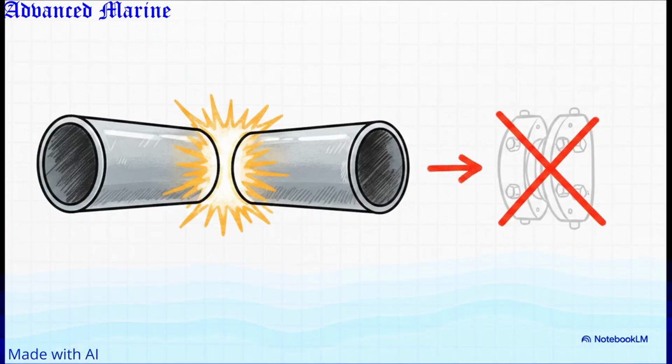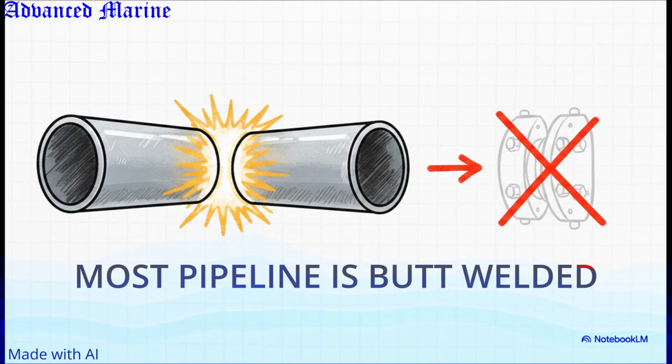Honestly, the absolute best defense is simply removing the opportunity for leaks entirely. In a state-of-the-art ammonia system, engineers will just weld the majority of the pipeline directly together. By physically fusing the metal, you completely eliminate the mechanical joints that have to rely on gaskets. We minimize open joints wherever physically possible. Flanges, those bolted, gasketed connections, are strictly restricted only to areas where small instrumentation has to be removed for maintenance or calibration. Every removed flange is a removed risk. It's as simple as that.